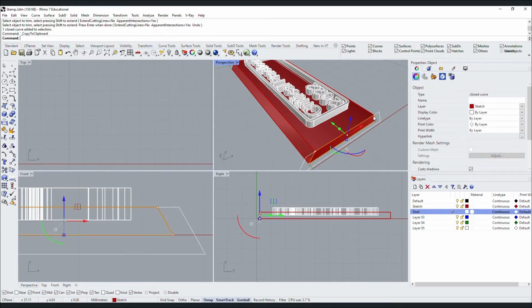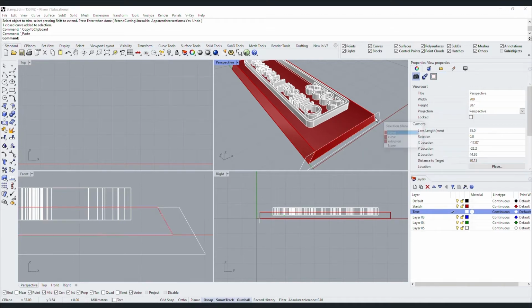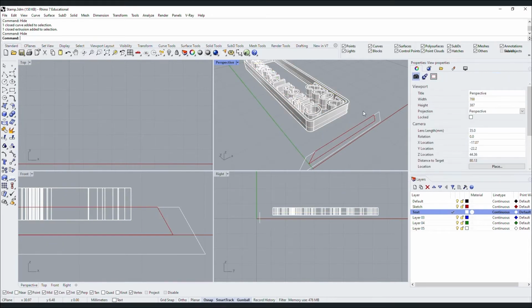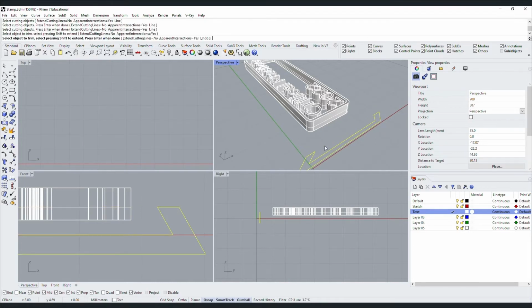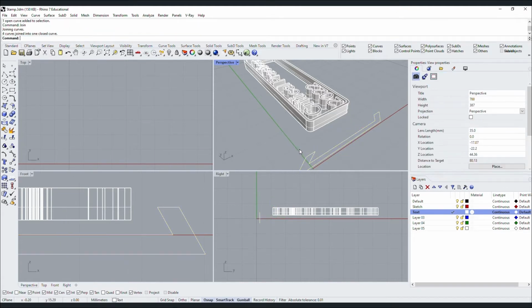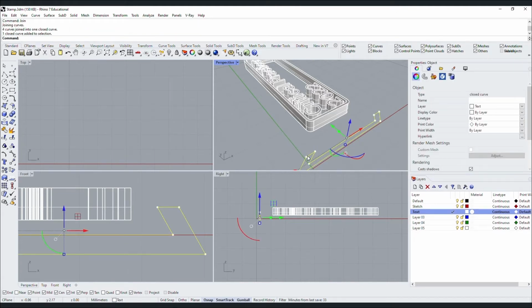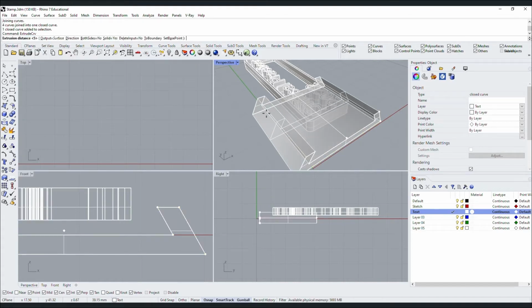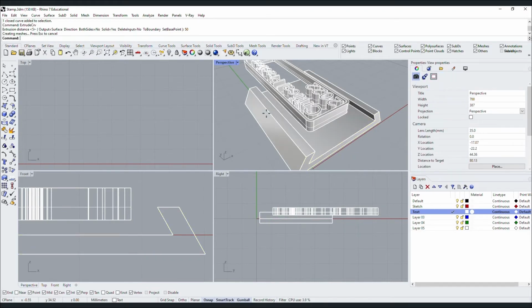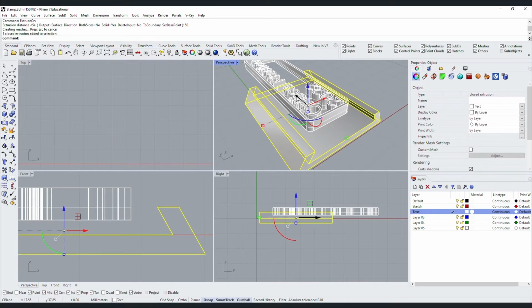Now it's a bit tricky to edit, so I'm going to hide the polysurface extrusion in this case. But before that, I copied it by Control C, Control V, just to have another editing option later on. Same trim and join command. So you have one same color, that means they are all in one same layer and they're all joined closed curves. Again, extrude. This is going to be a bit smaller than 90 mm, so I'm going to put 50 mm.